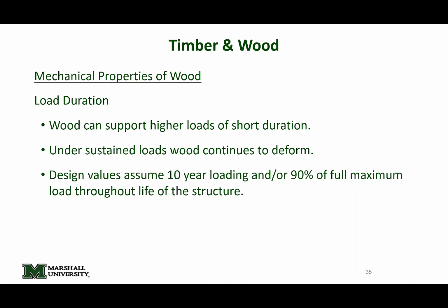One big parameter that affects wood's behavior is the load duration, okay? If you take an element of wood and put, let's say, 100 pounds on it for 5 minutes, the wood will respond better to that load than if you put that 100 pounds on it and leave it there for 20 years, okay? Wood has much higher capacity if the load is applied over a short duration.